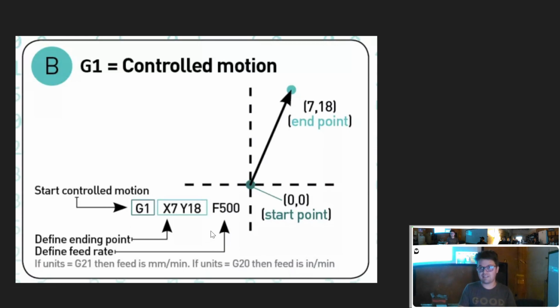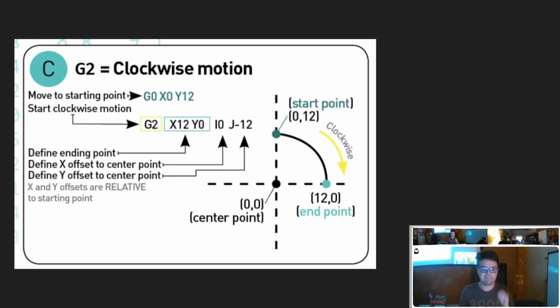Now, with both of these commands, almost all the arguments are optional. If I don't specify a feed rate on a G1 command, it will use the most recent previous feed rate that was fed into any other command. If I do not feed it an X position, it will assume the same X position I'm currently at and not change X. So you can just say G1 Y1, and it will move to Y1. You can also, and this is buck wild, say Y2, and it will assume we're still in G1 and also move to Y2. You don't have to know all of this. There's just a lot of peculiarities of how these machines go.